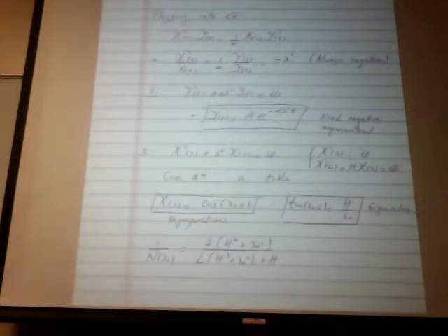Okay. So then we put it all together. And essentially, the temperature T of x and t is equal to the summation from n equals 1 to infinity of Cn cosine of lambda n x e to the minus alpha lambda n squared t.